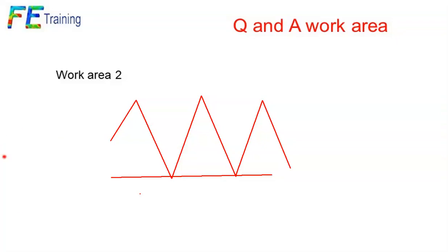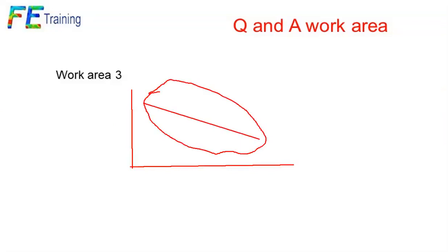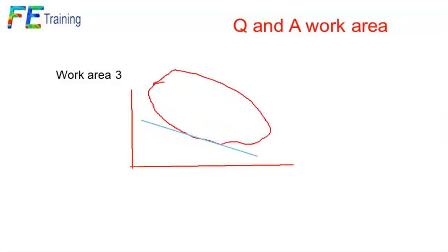Again, going to a fresh sheet. We've got an SN curve, and we're assuming that that's been created. And again, remembering it's a log-log curve, there it is, but we've got a whole cloud of data surrounding that. So we're actually doing the best fit through there. So do we take the mean curve, say 50% through there, or do we drop the curve down so that we are at kind of the lower bound? The worst test data we'll ever find is at that lower bound. That's going to be incredibly conservative.